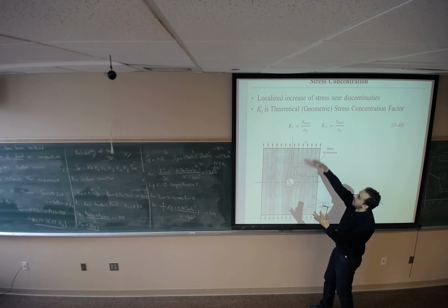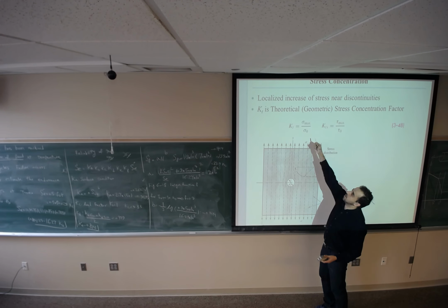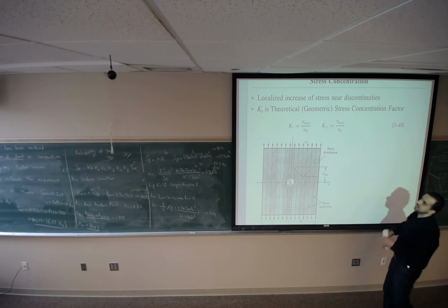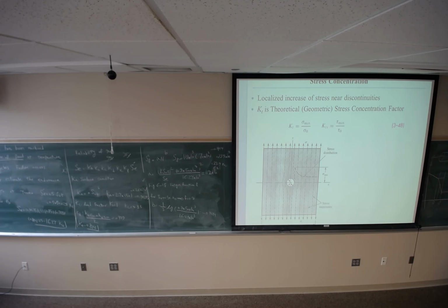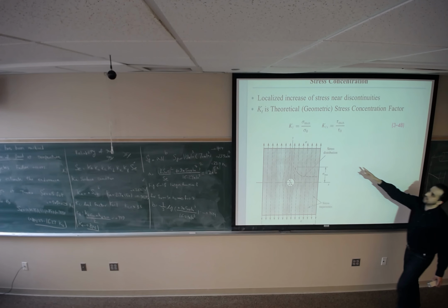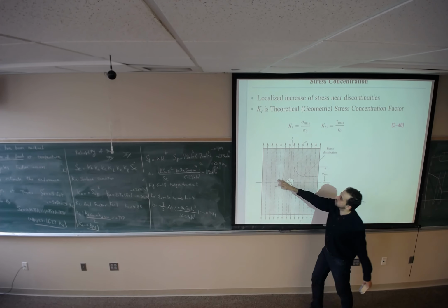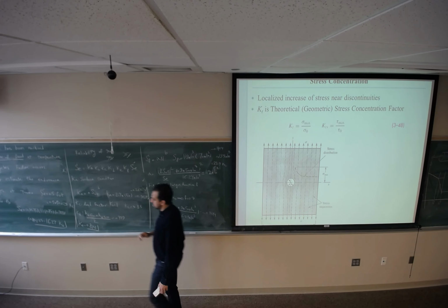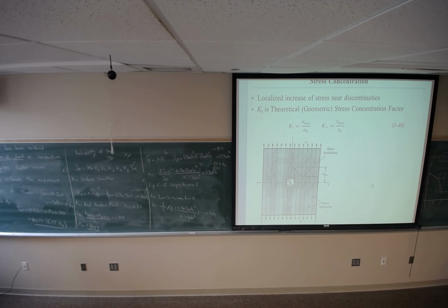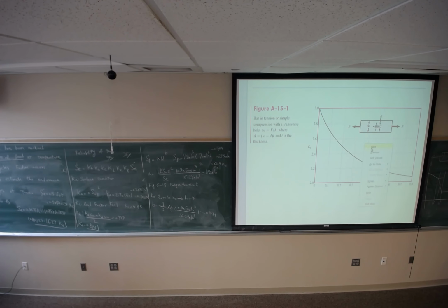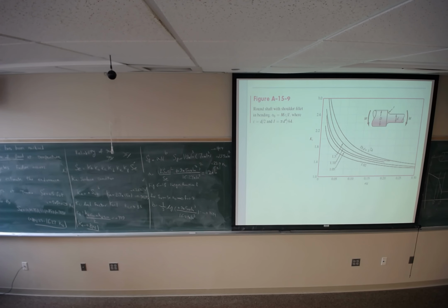The actual stress, sigma max, is greater than the theoretical stress, which comes from dividing force by the cross section. So we defined KT in that chapter, and we learned how to find KT by using the table A15 for the different loadings and components.